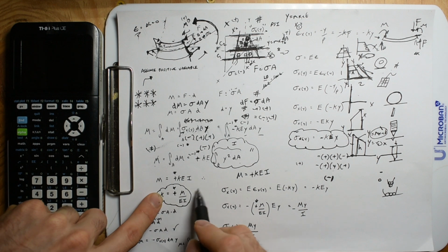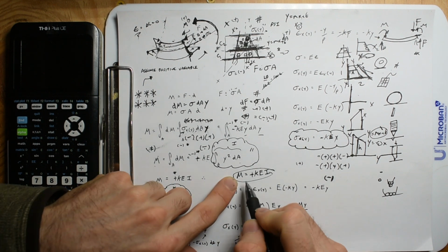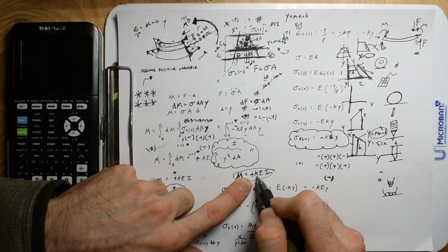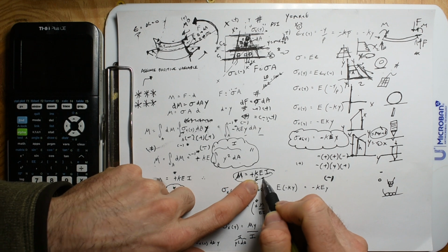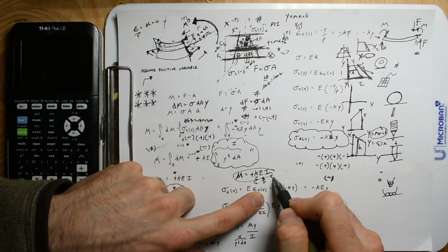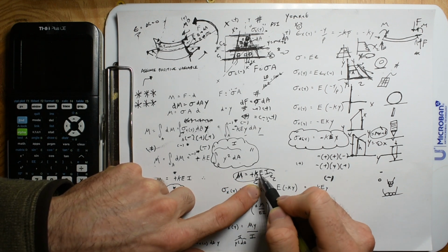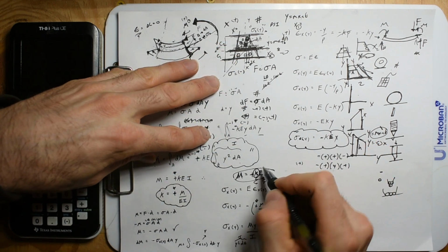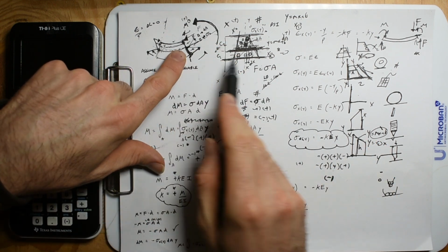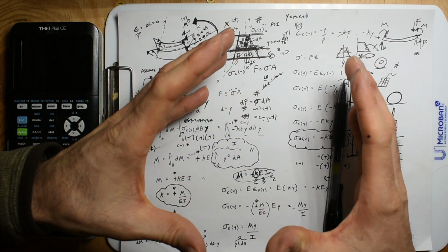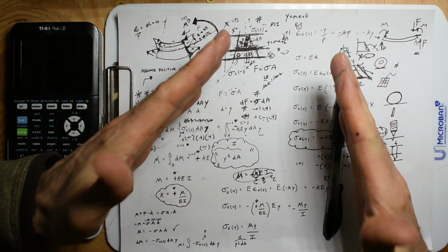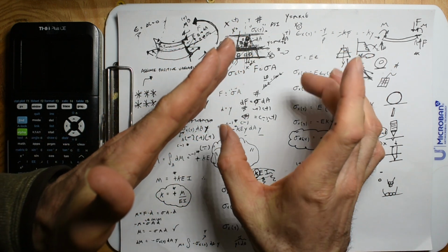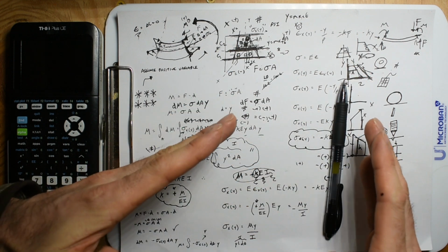Now you take this equation, and this says that the moment is equal to the curvature times the material property times the shape, and I guess that's cool. And the curvature is the reason, and it should make sense. We talked about how the curvature was changing the shape. The change in shape made things shorter, made things longer.